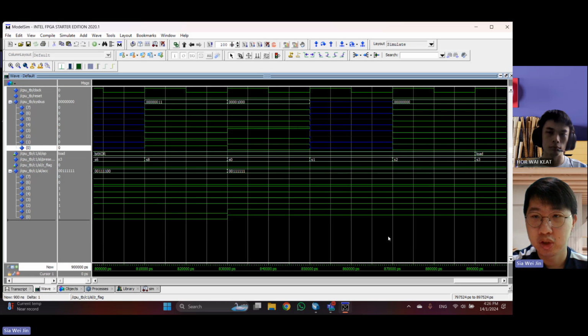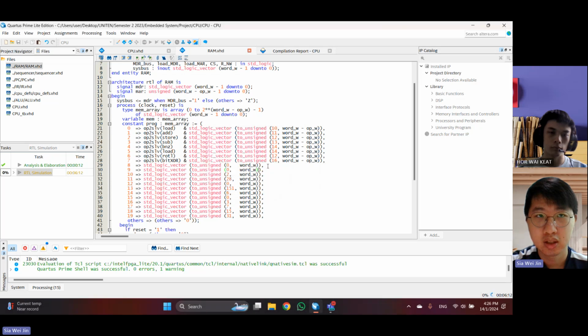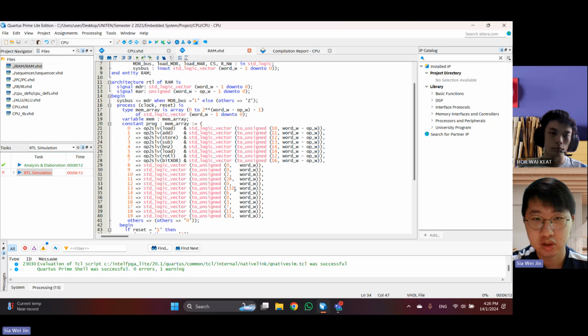So now we'll be simulating with the Z flag equal to 1. In order to simulate that, we have to change the content of the subtraction to get 0 for the accumulator. Previously the result of the addition was 1E, so we have to subtract 1E again, which in decimal is 30. So we'll get 0. Let's see what happened.